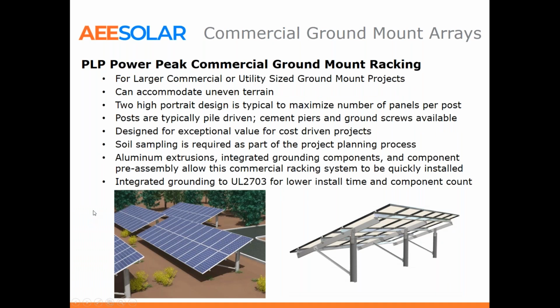So conversely, for very large projects, we do have the PLP Power Peak commercial ground racking system. This is either pile driven, or you could mount the piers in cement. This is a 2-high portrait system, so we consider these as tables. We want to know what size of tables and the deployment there. It is a fixed tilt. I believe 20 degrees. I forget exactly what the tilt is, but it is a fixed tilt system, so we can't alter the tilt.